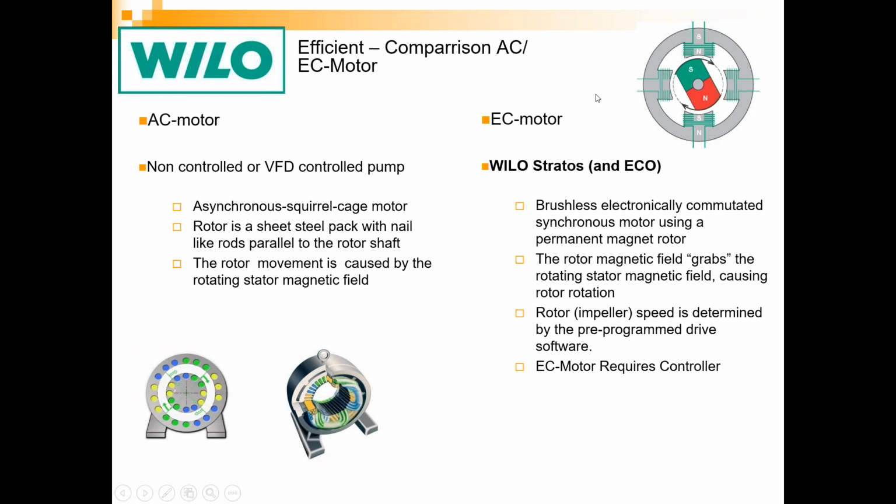One of the big advantages of electronically commutated motors comes when you're talking about motor slip. In an asynchronous type motor, you're constantly chasing a rotating magnetic field, which has a much greater slip than an electronically commutated motor. That slip becomes greater and greater on a VFD controlled pump, as the VFD turns speed down by lowering the hertz on that drive.